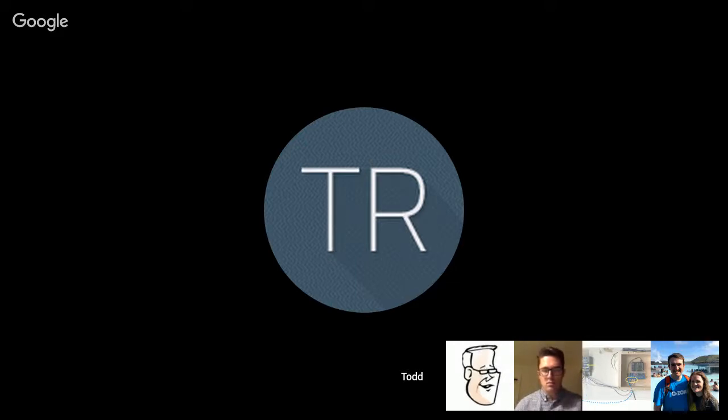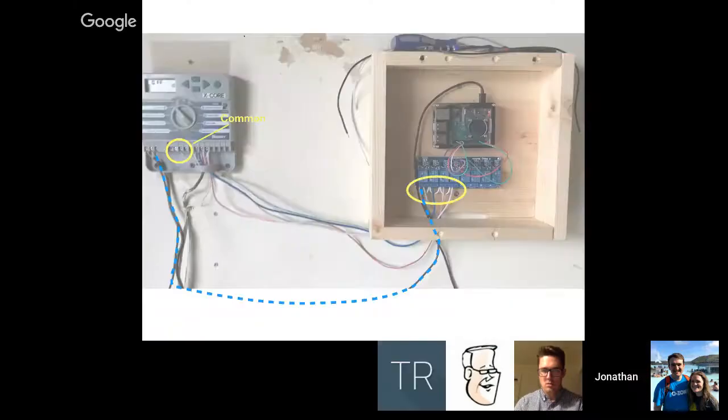So did you need to hook up that second wire, the non-24-volt wire that comes from the power adapter? Yeah. Okay. And that just went to the common? So I didn't have to touch the common here. I just found whichever one was the hot lead, whichever one was not connected to common, and I ran it over to my relay. I plugged it into my relay, and then I daisy chained it across all the other parts. I turned a zone on, and then I touched one of my screw leads for the 24 volt, and it didn't turn on. Then I touched the other one, and it did, and that's where I kept it.